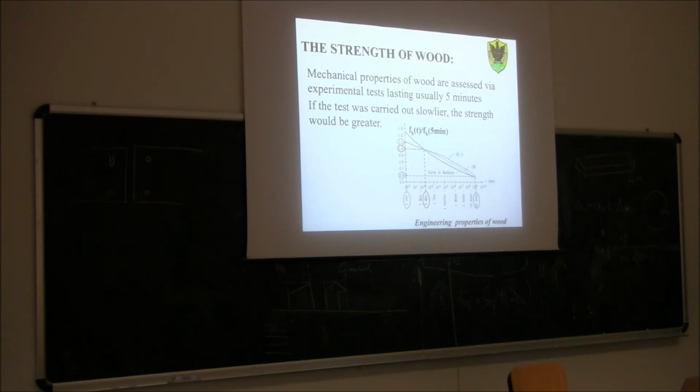For the storage building, which value of strength would you use? The strength for 5 minutes, for 1 second, for 50 years, for 1 year? For a storage, a coal depot, a library. The library will have all these books there for 50 years and more. The long one, because in this case the load is a long duration load.